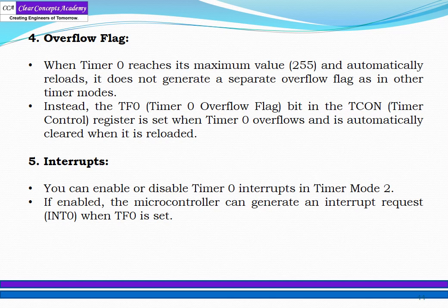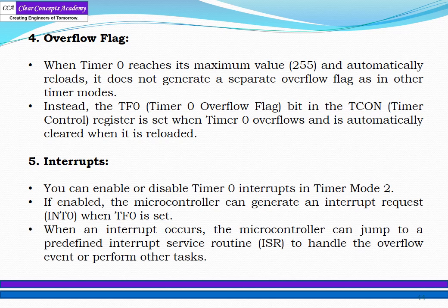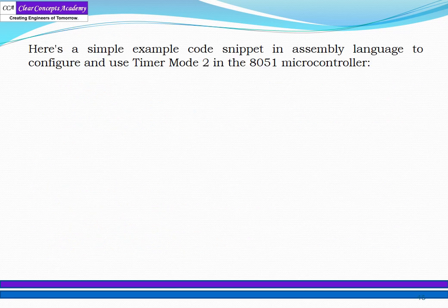If you want to attend some interrupt service routine, then you have to enable the interrupt for the timer 0 overflow by setting a proper value in the IE register. When an interrupt occurs, the microcontroller can jump to a predefined interrupt service routine, that is ISR, to handle the overflow event or perform other tasks.